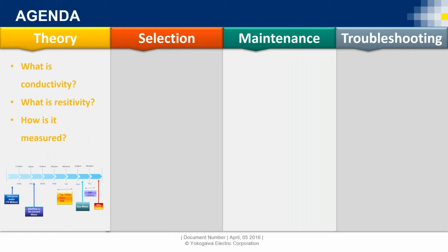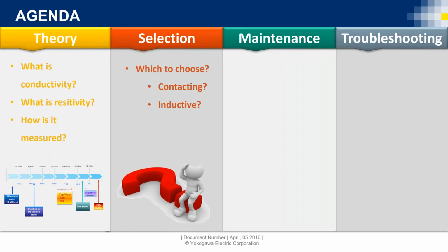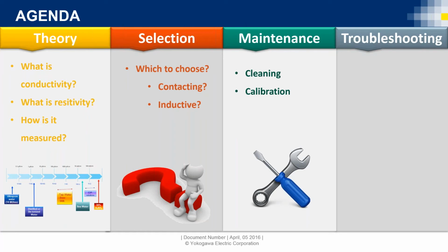So I wanted to tell you about the differences in measuring conductivity, if we're doing that, or if we're doing very ultra pure water where we may use it as resistance or resistivity reading, and then also explain the difference between the two types of measurements, because you may also have, on your mixed bed or your ion exchangers, your polishers, percent concentration readings up there on your regen line. So talk about the difference between contacting and inductive, the two terms that are used for how to measure conductivity.